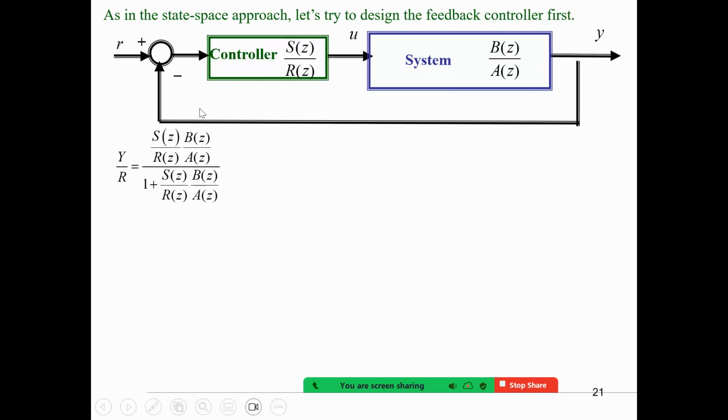And this open loop transfer function will be the same, right? Like the feed-forward transfer function. This is how we write the transfer function this way. And after some manipulation, we will get the form of this closed loop transfer function. Now we're going to design S and R such that the closed loop transfer function, A_CL, matches the reference model multiplied by A naught.